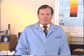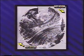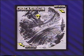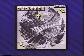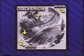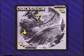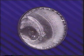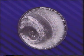Under low or moderate overloads, a rotating shaft may fail as a result of a single fatigue crack. When the shaft is always rotated in the same direction, the crack usually advances asymmetrically. That is, the direction of beach marks shifts in a direction opposite to the direction of shaft rotation. Asymmetric fatigue crack growth indicates bending and the direction of rotation.